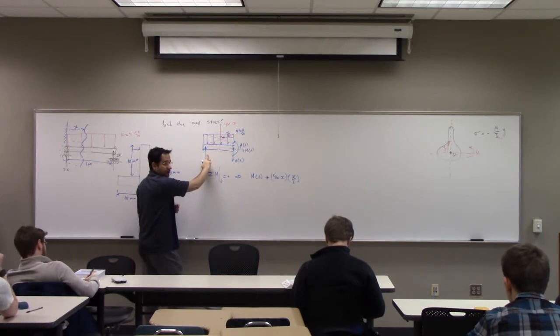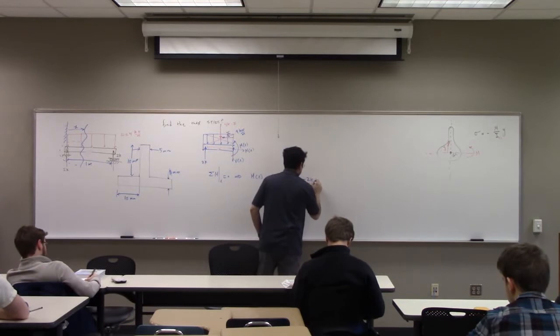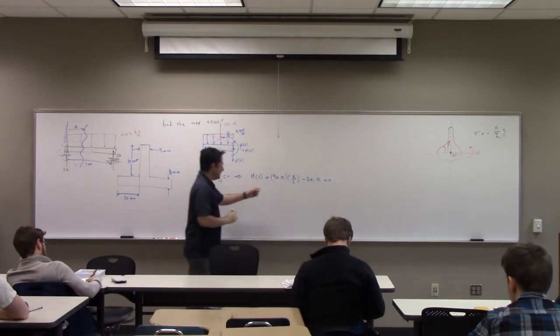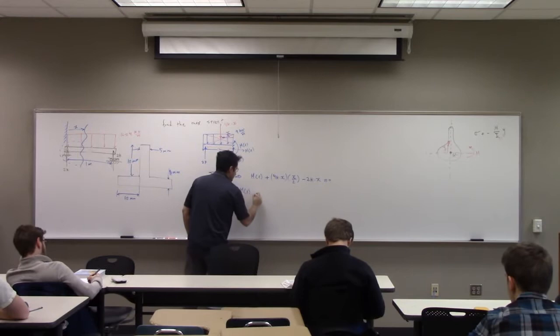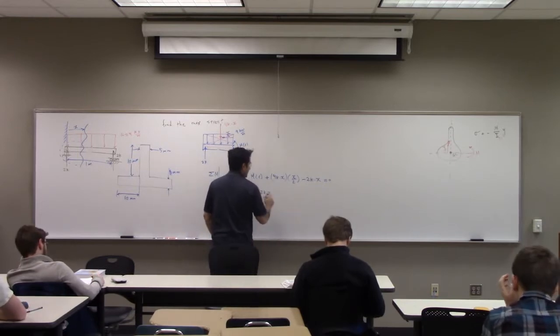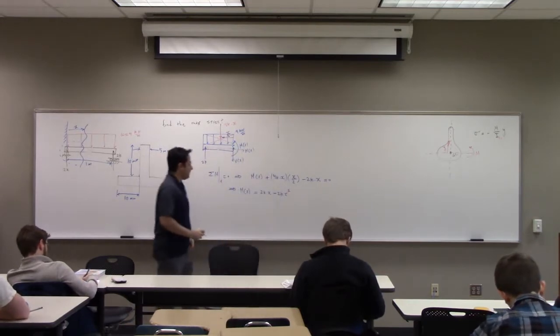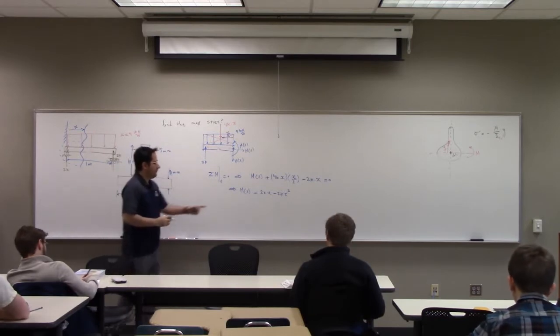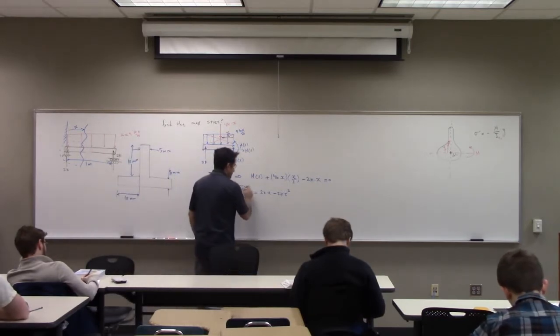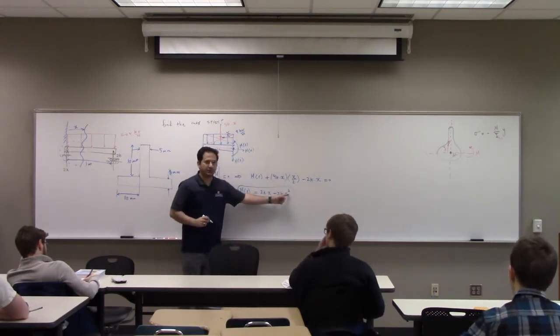Then you go to the next one. For this one, you have what? Negative 2K times x, is equal to 0. Then I find my M(x) positive, negative 2K x squared. So this is my moment distribution. It's kind of parabolic, second order.